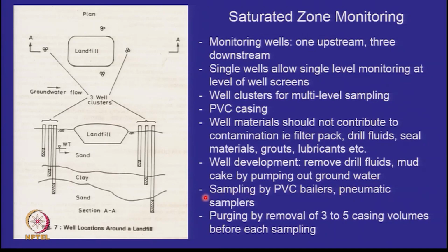To pick up the groundwater samples, we would like to use PVC balers or PVC pneumatic samplers. And in any case, whenever we want to go and sample at a particular location, suppose I want to pick up a sample today, then I want to come back after a month and pick up a sample, I don't just send my sampler to this level.